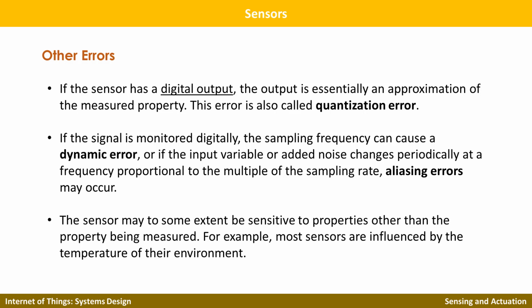In simpler terms, if the outside world is changing at a faster frequency than the frequency of the sensor, which actually samples the phenomena, then of course it could end up with an error, because the outside world is changing fast and the sensor cannot sample enough to capture the changes of the real world.